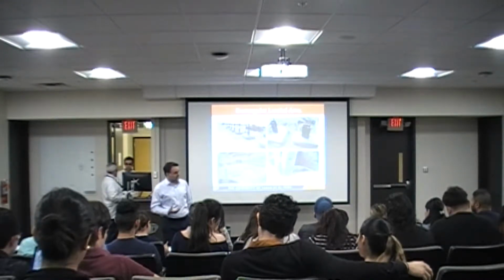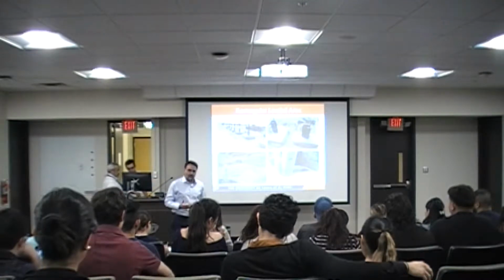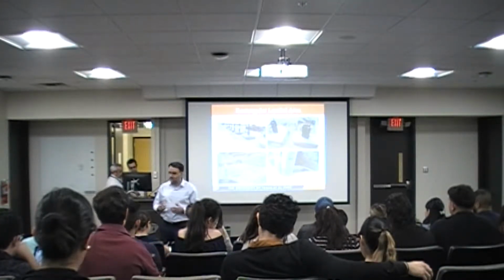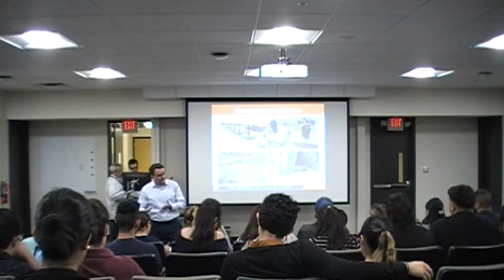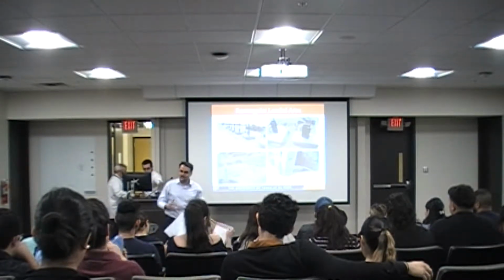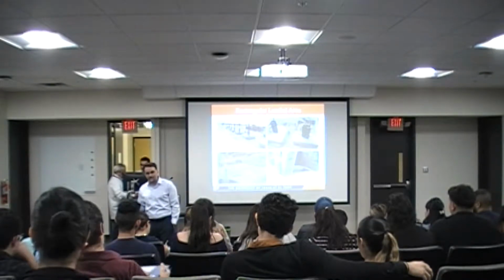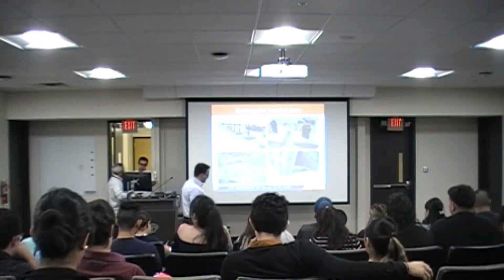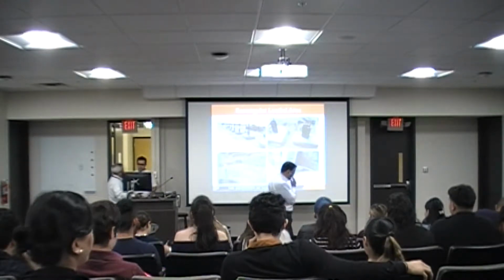But for the foundation of this building, depending on the mode of failure, we have a factor of safety between 1.5 and 2. So that means that basically if this foundation tilts a little bit, you might see some cracks. Hopefully there's not going to be fatalities there, and then you can go in and take some sort of measures. So that's basically what we mean when we're talking about the factor of safety.